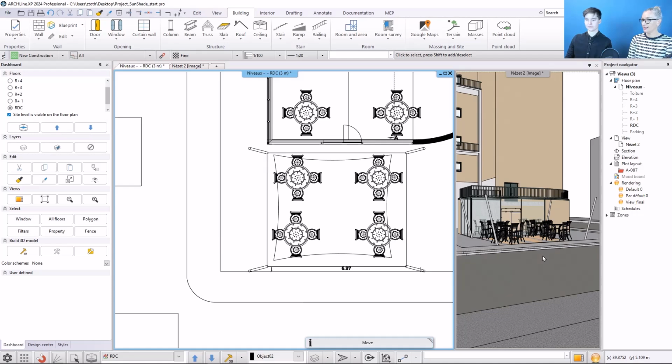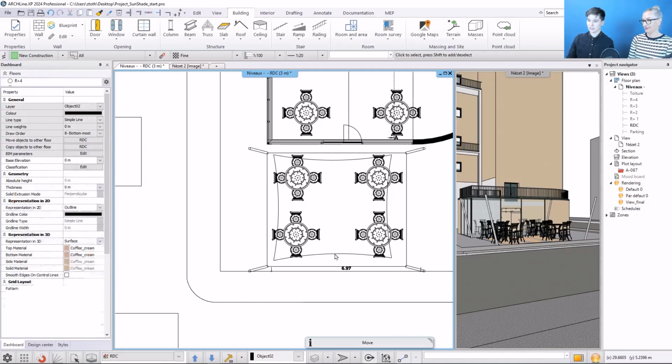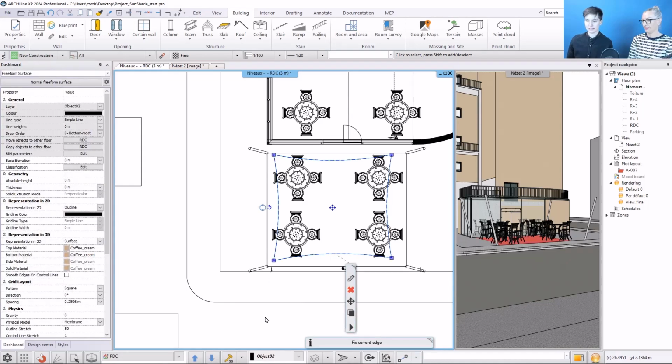Okay, but it's on the floor now. Yes, we need to modify its position. I will click on it, and since the columns are 3.3 meters high and the textile is hanging attached to the tops, its height should be 2.65 meters.